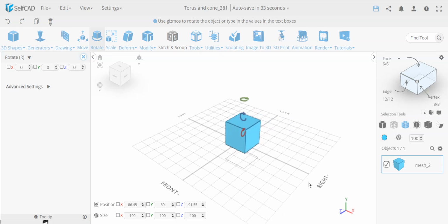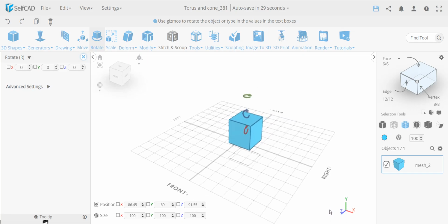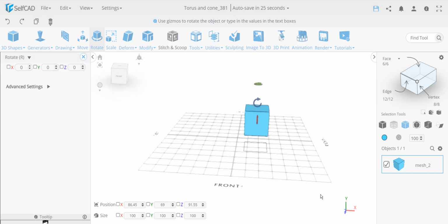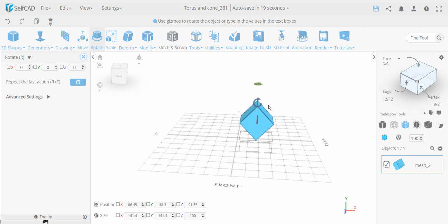If you look over here, it's very easy to see. I always look at these guides. If I want to know what I'm going to rotate around, you can think about it as rotating around this guide. So if I take this blue one, it means I'm going to rotate around it, and I'm moving it by 45 degrees, let's say. If you want more exact precision, there's a setting over here for minimum step size, and that's the default. I guess it's 5. I don't remember if I said it, but that's the default. If it's 5, it will be in lock steps of 5, so it will be easier to position.